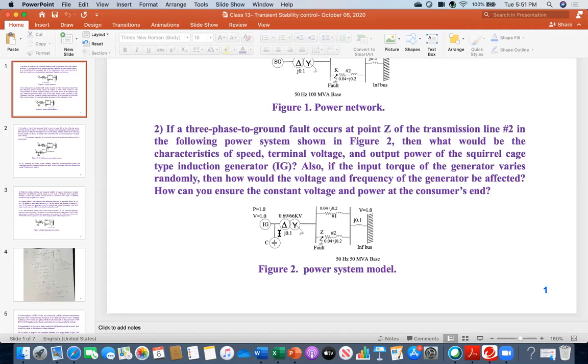Now, there is one capacitor connected. That is 24 hours working. But this is for the normal situation. Normal situation means its function, because for its operation, the induction generator needs reactive power from the system. So that is compensated by this capacitor. It cannot do beyond that. This means if some additional fluctuation is coming, which is from the input or a fault happened,